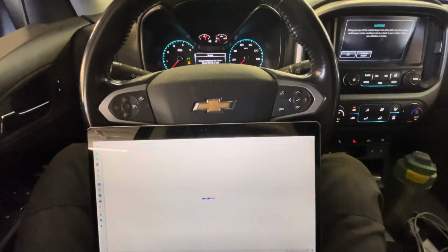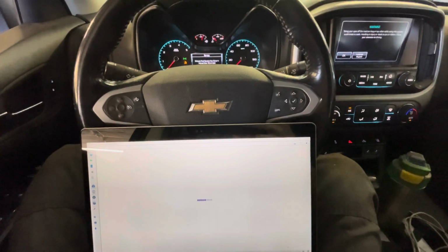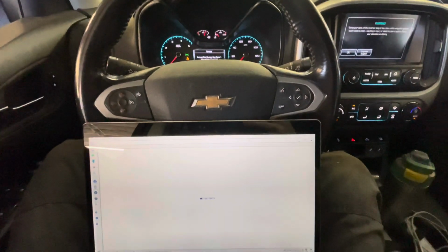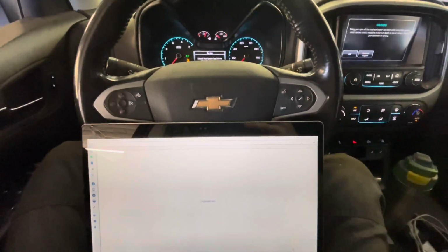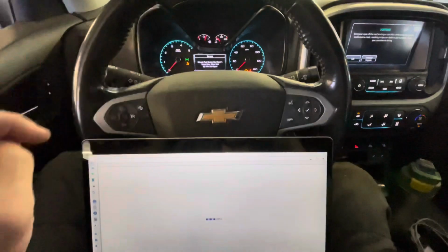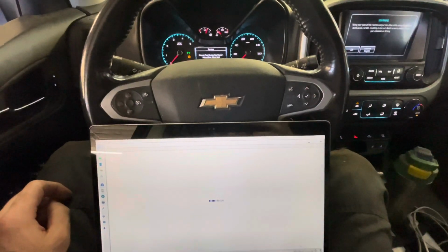Okay, so we're reassembled. We're going to do the reductant system leak test to verify we are now running the proper specified pressure, and then we also need to deal with the exhaust system message after that. So give me a second here.